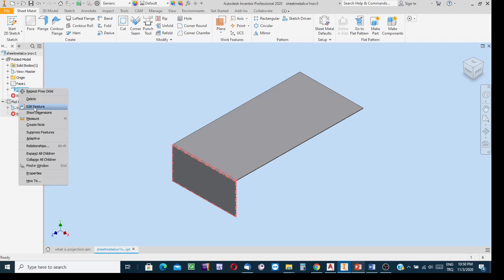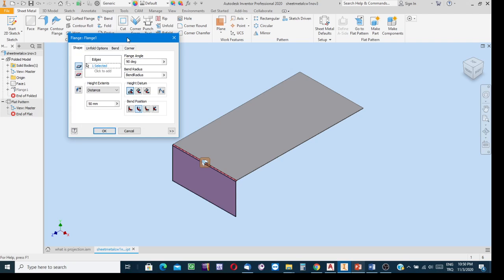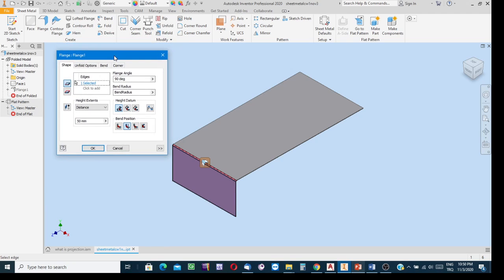You know, it is always true: if you have a feature and need to edit it in shape or in size, then select the edit feature option to be able to change the process parameter. Select the edit sketch option, if there is an associated sketch, of course, to modify the sketch in shape or in size. But here, I'm going to change the parameter of the process, so select the edit feature option. And it is the same dialog box, the flange creation dialog box.